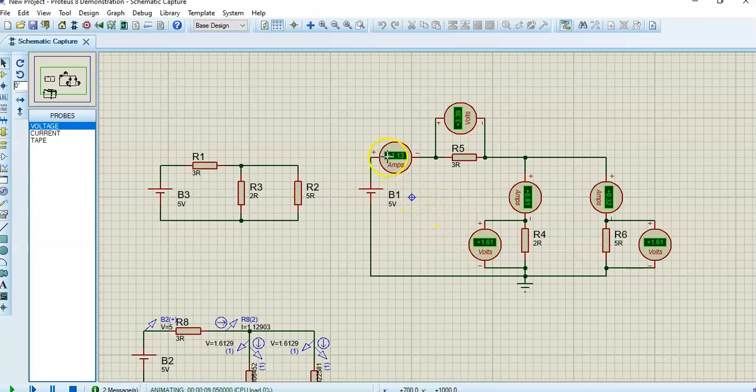You know that the current 1.13 amps, which is in this branch, gets split into the two parallel branches here. When you add up the current in this branch, 0.81, and the current in this branch, these two should add up to 1.13. This is what Kirchhoff's current law says. The current into the node must be the same as the current out of the node. In other words, the algebraic sum of the currents at any node must be equal to 0. This is just a definition you have to remember.